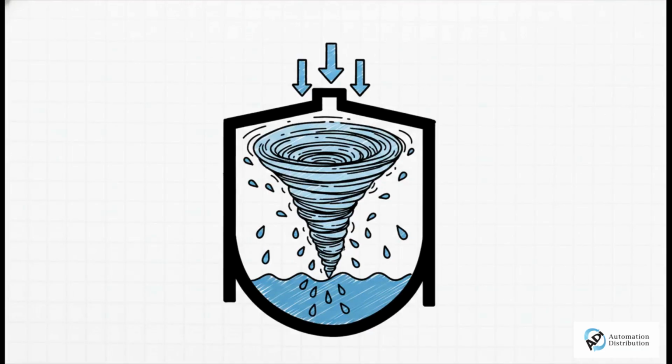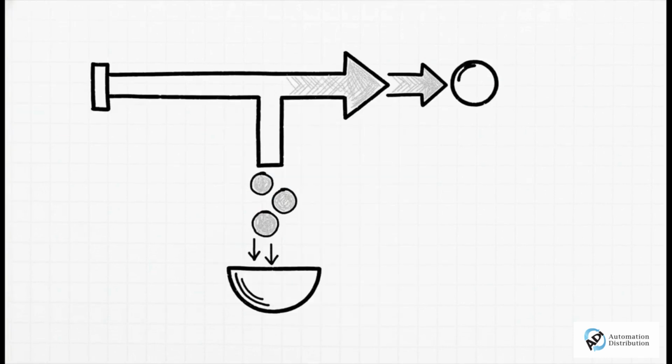And that brings us to step 2, water separators. These devices mechanically yank liquid droplets right out of the moving airstream. They use centrifugal force or resin filter elements to do this. For instance, if you look at technologies like SMC's AFF Series water separator and filter, they can achieve up to a 99% water removal rate for droplets and solid particulates. Their specific design prevents the filter element from getting saturated too early, pulling out those droplets so they simply never reach your tools.